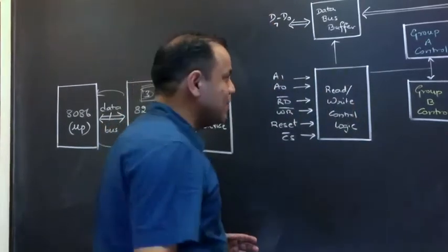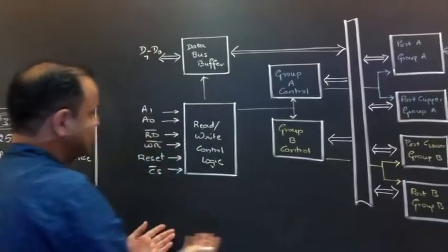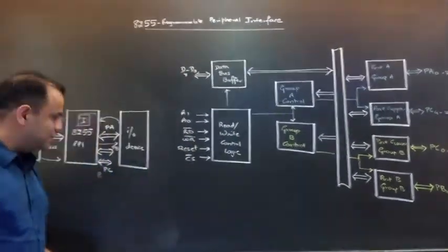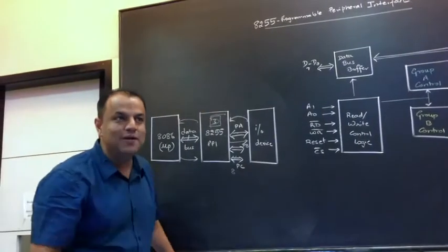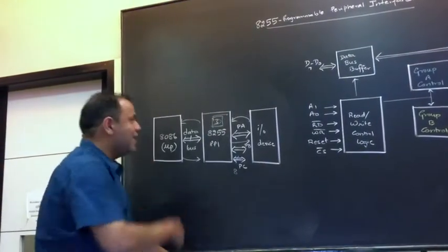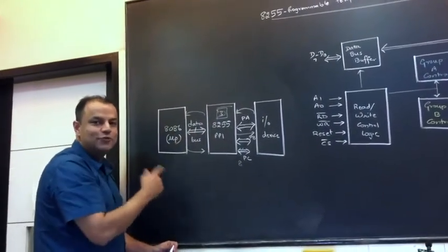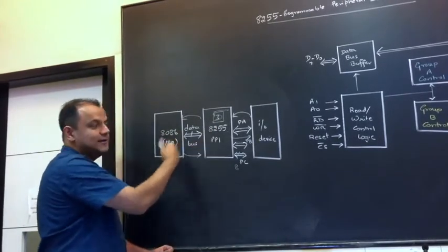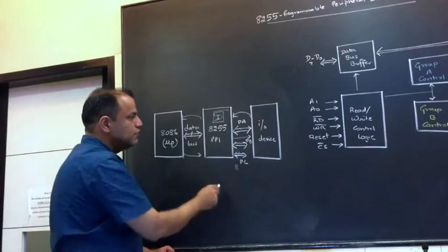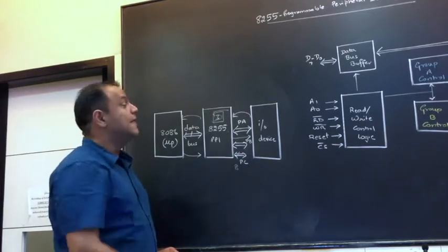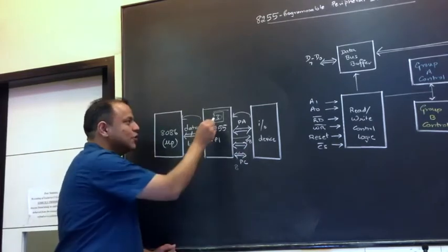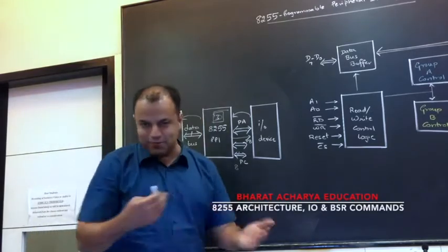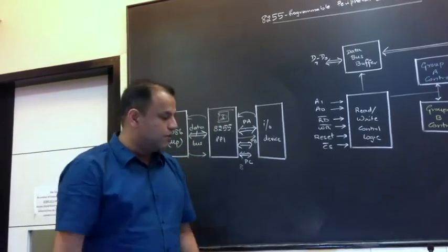In 8255, look here. In the whole architecture of 8255, there is no clock. That means 8255 doesn't understand time. That means it doesn't care how long the processor takes to get the data. Till the time the processor doesn't ask for the data and take the data, 8255 will not give permission for the next data. That means no matter what happens, you will not lose the number 3. And 3 is just symbolic. That means any data transferred in the system will not be lost.